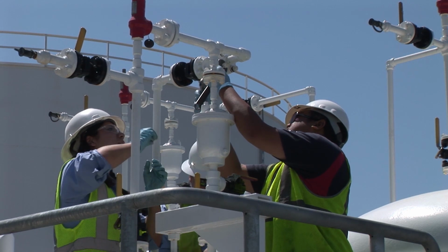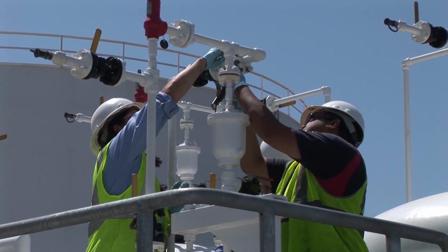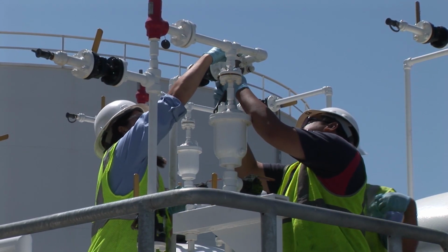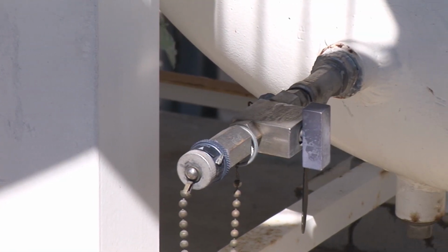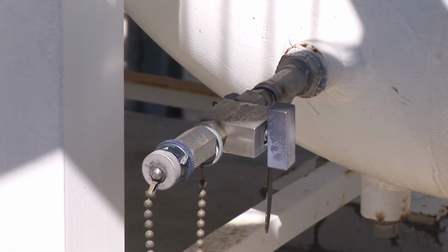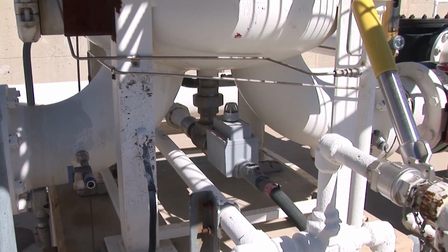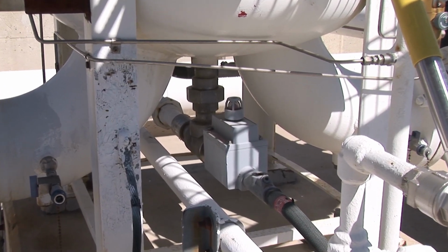The pressure relief valve and air eliminator should be removed periodically and tested. Repair or replace any leaking drain and sample valves. And before cold weather hits, you should activate and check sump heaters. Continue to check them during the winter.